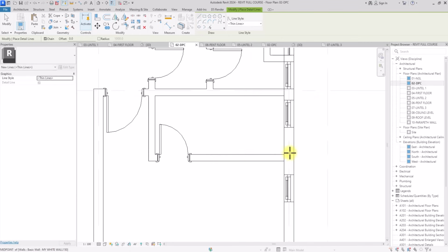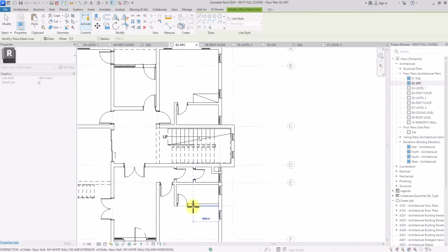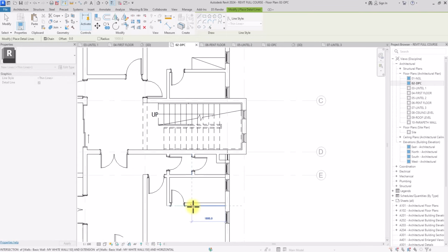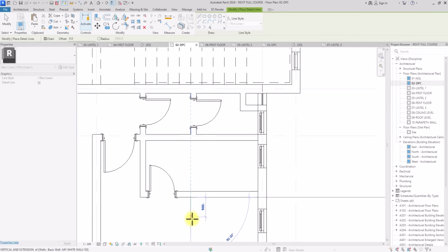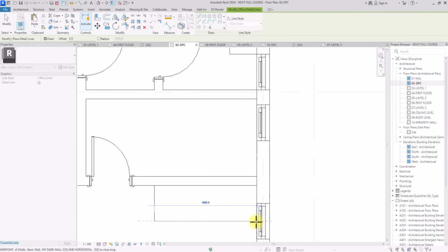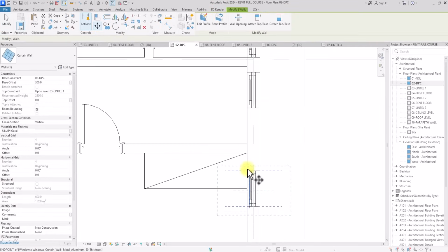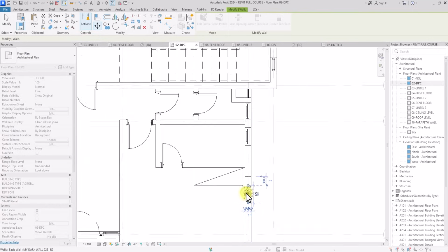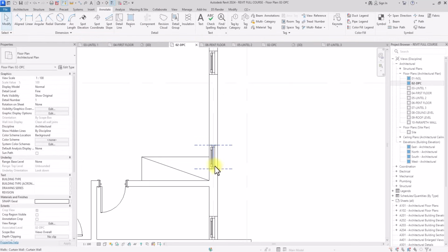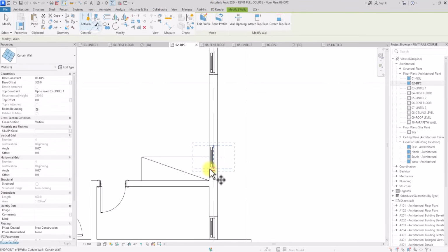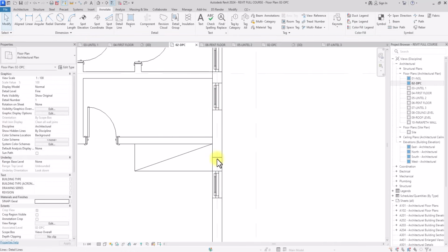and I'm going to do the same for this room as well. Do this, project it at 1.8. I'm going to project it at 600. Then I'm just going to draw a line on this bedroom. So now I'm just going to move this fenestration. I'm going to move this window by 300 so it won't be obstructing this wardrobe. I'm also going to do the same for this. So now I'm going to delete this line here.